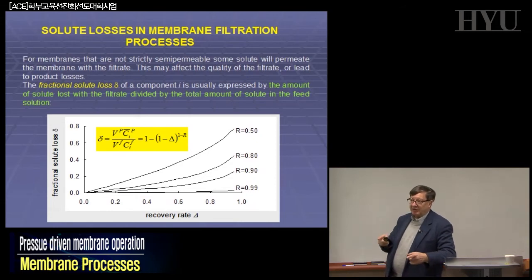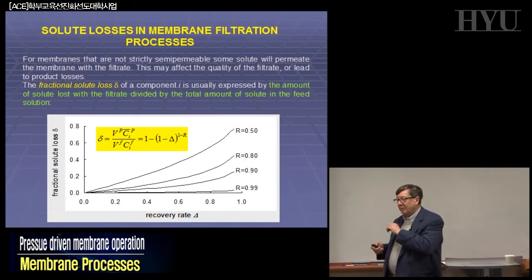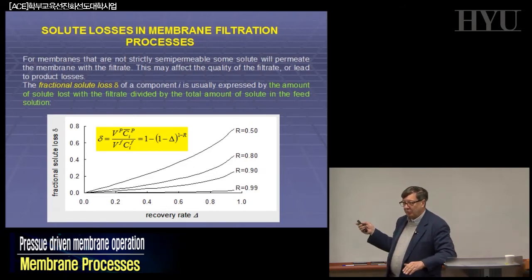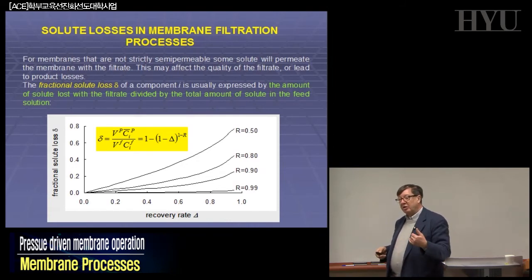Because now with the new standards that you have for electronics, we have to remove not only salts, not only sodium chloride or any other salt, but also all the dissolved gas. We have to remove oxygen to a molecular level, no oxygen at all. For doing this, RO does not work. And so one of the first applications of membrane contactors, membrane distillation, was for the ultra-pure water for the electronic industry, where you can remove oxygen through membrane contactors for the standard we need today.